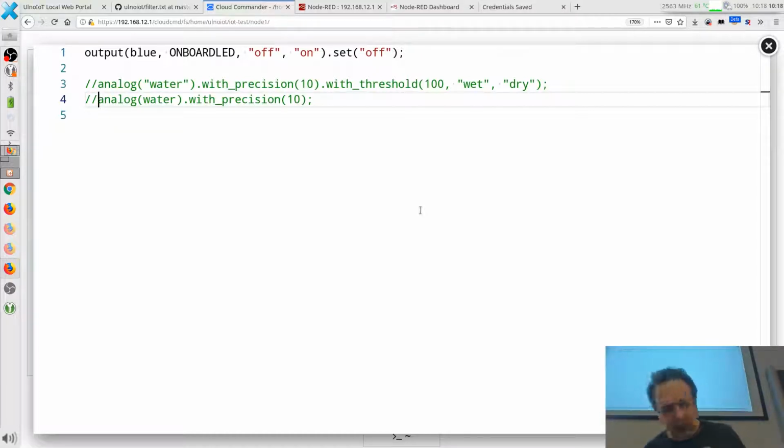So we need some more cables. About 4. 1, 2, 3, 4. And so I wire them all up. The problem is usually they write something like RGB on the LED, but often it's wrong. So you have to play a little bit and figure out what is really the red line, what is the green line, and so on.